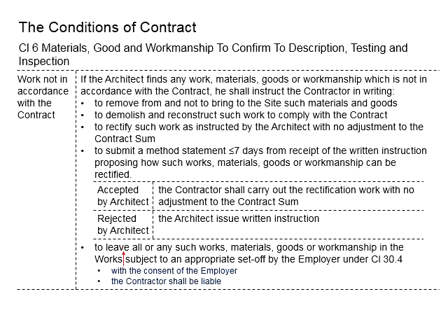Or the architect may ask for a method statement from the contractor, giving the contractor the flexibility in how the contractor intends to rectify it so that the entire thing meets the requirement. A method statement is the description or the procedures stating how the contractor intends to rectify it. This will be vetted by the architect as to whether the proposed method statement is workable or acceptable, and this is subject to the acceptance by the architect. The duration is less than 7 days for the contractor to come up with the method statement. After the method statement is submitted, the architect will look into it.